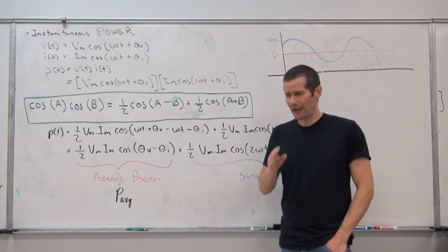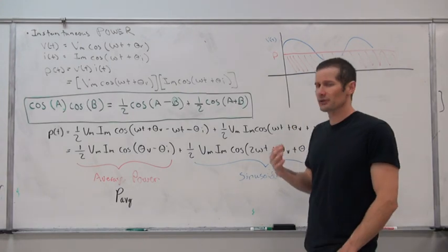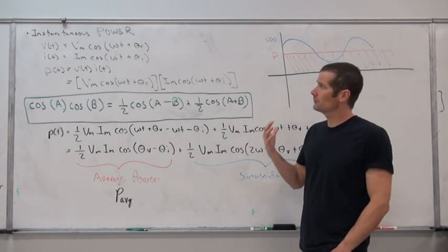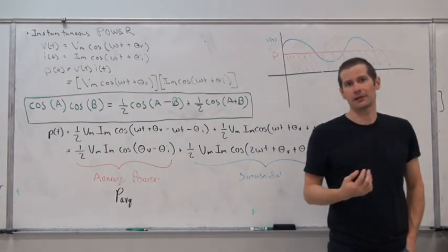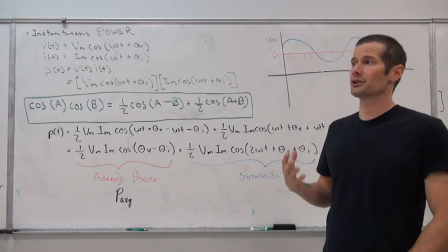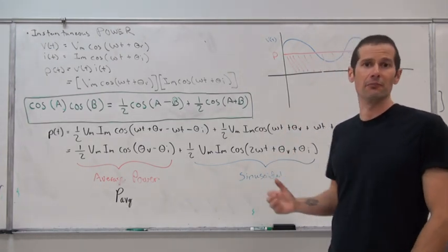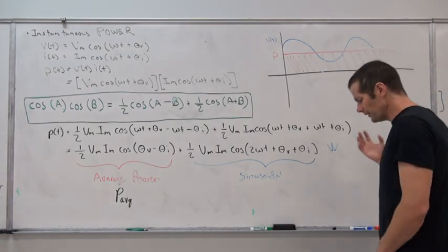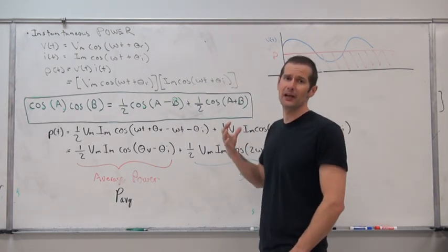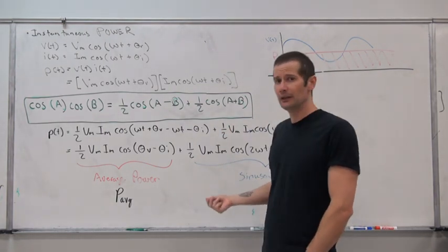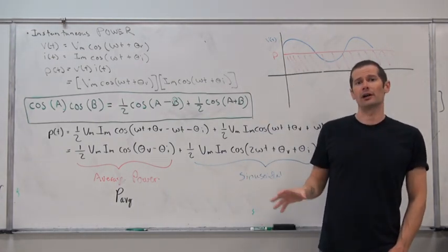Now, power is not something that we discuss too much within circuits 1, because in circuits 2 we actually reinforce that. Power by a base definition is the rate at which energy is being expended within an electrical system. So the base equation for that is always going to be P is equal to V times I, so voltage times current. And within a DC system, it's always measured in watts.